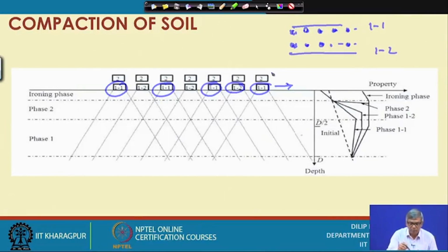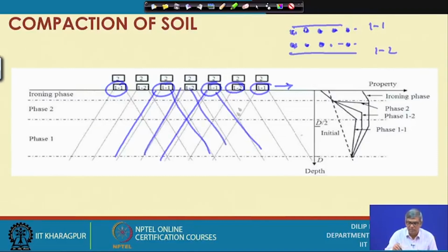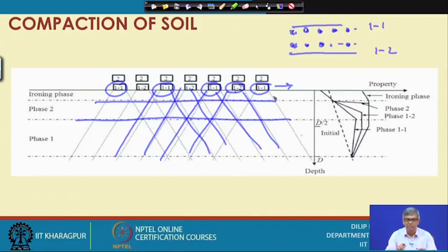That is the way: when it drops here, its effect will go from this to this, and when you put this one, the effect goes from this to this, and when you put here, it goes from this to this. Like that, there is overlapping in the area, so compaction is going on. And when you go to the higher layer, again it will compact, and that overlapping will become closer. This way your compaction will be achieved. So there will be different patterns one can use according to the requirement.